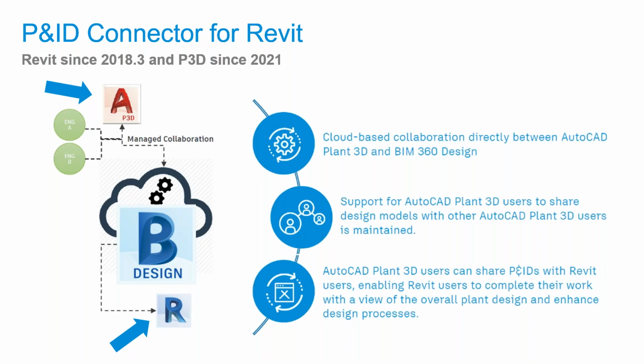And then Lucas, just to answer your question, you talked about mining projects in Plant 3D. I'll just give you some quick tips, especially when you're dealing with point clouds and large civil backgrounds. With the point cloud, you're probably going to look at decimation and minimizing the point cloud area as much as possible. With Plant 3D and mining, where there's a lot of equipment, you have to change the level of detail.